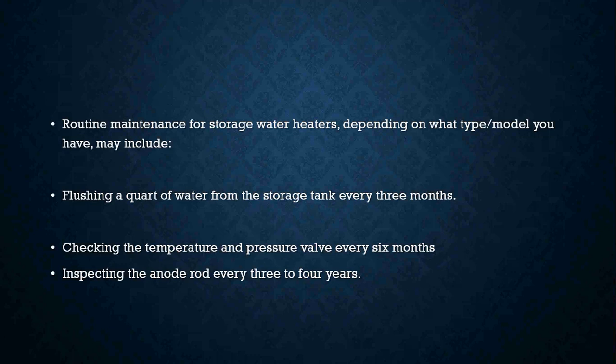Okay, inspecting the anode rod every 3 or 4 months in a water heater. Okay, an anode rod is what actually takes out any sort of impurities in the water. Okay, calcium, iron, stuff like that. The anode rod will actually catch all of those impurities. If we have high concentrations of like calcium and iron in our water, we actually can deteriorate the metal in the construction of the water heater. So every once in a while you're going to want to maybe do that.